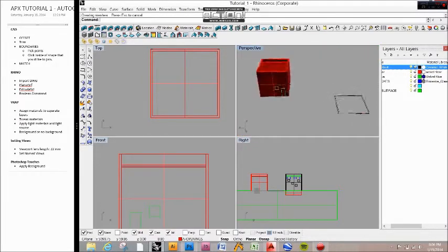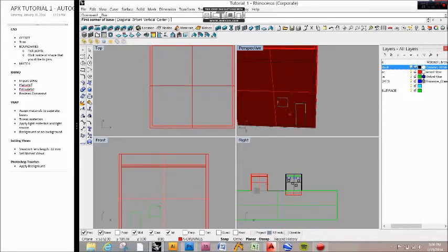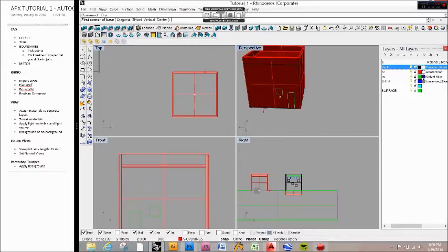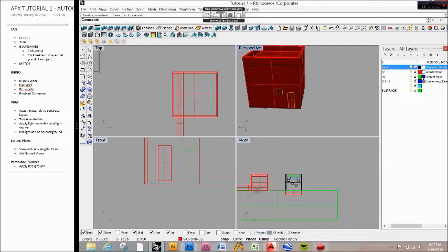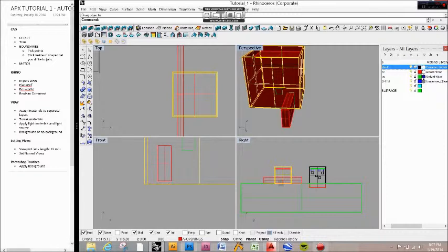Great. So now we want to start adding the apertures, your windows and your doors. The quickest way would be creating a form over it, making sure it goes through your desired form, hitting the object that's going to stay first, right-clicking this button right here, hitting this Boolean difference button, and then specifying what's going to cut through your form.